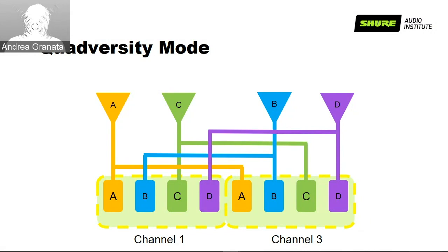When you have a very high noise floor, all you can do is to keep your antennas as close as possible. And with QuadVersity, instead of having just 2 antennas, mostly on the side of a stage or even in the center of a stage, they added a distributed antenna every 12 meters on stage, covering a complete 50 by 100 meters area with absolute peace of mind.